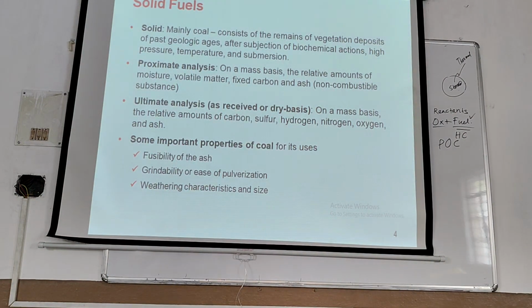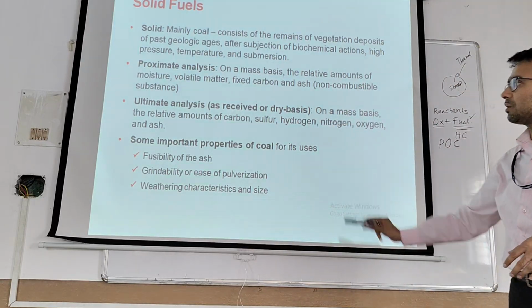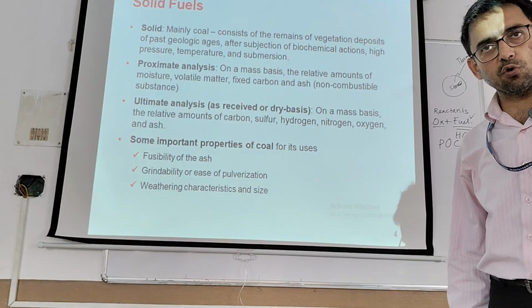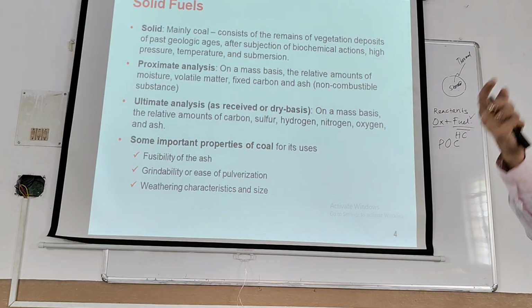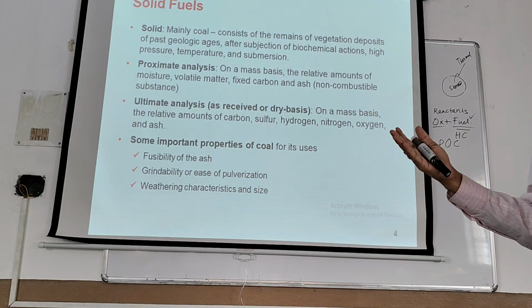This is called gravimetric analysis. Another is called volumetric analysis. For example, for exhaust gas, sometimes you will see volumetric analysis or gravimetric analysis. Volumetric means per unit volume and gravimetric means per unit mass. They are used to determine the constituents of the fuel. For example, you have some coal, then you analyze it so that you can calculate what the constituents are, and then go for